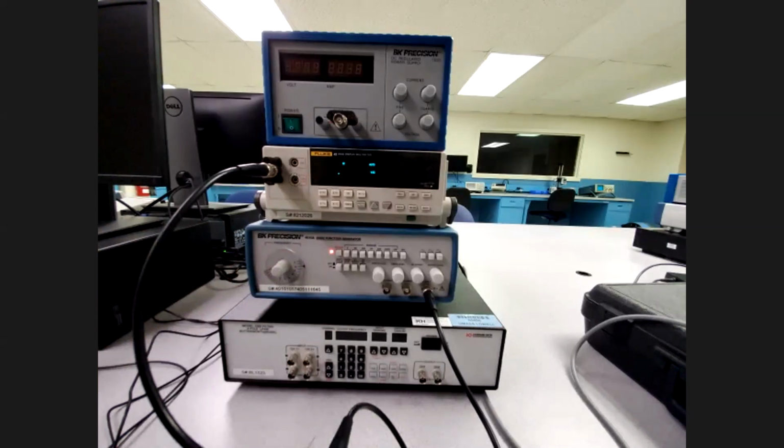Okay, so if you take a look at the multimeter, you can see that it's blinking. It's having a higher time calculating the voltage RMS, but I can see a constant number, and that's the one that we're gonna take. But let's do column B. For the oscilloscope, voltage peak to peak, we have 10 volts. For the multimeter voltage RMS, we have 2.72.